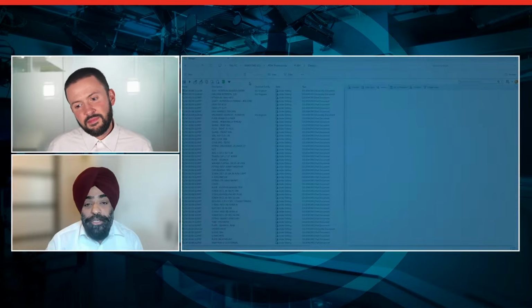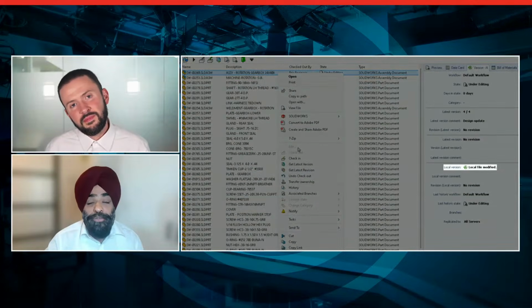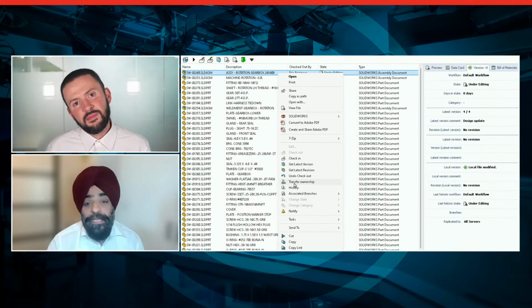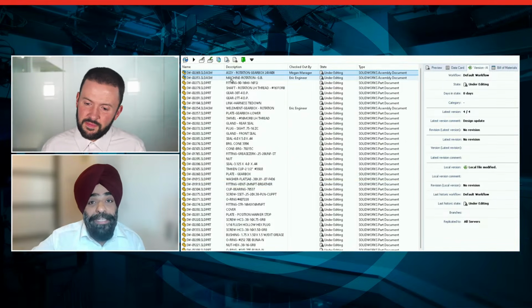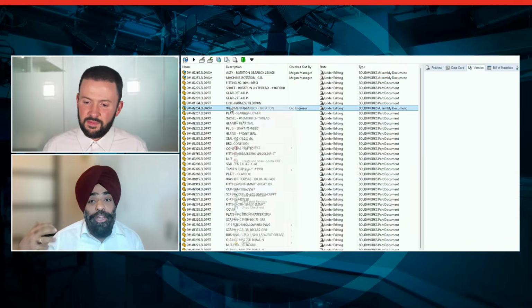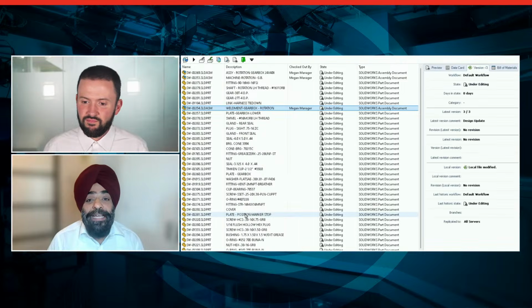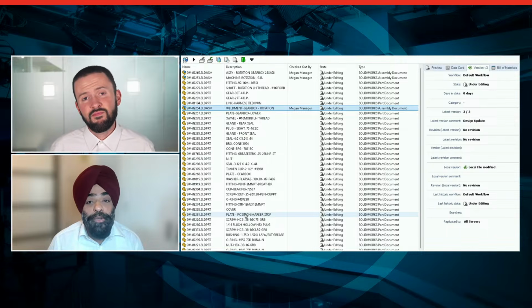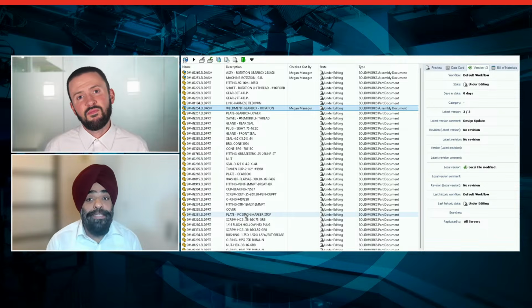So we are in a situation where Eric has either left the organization or we end up in a situation where we have a user machine crash. In such situations, we have some data which is locally saved, but it's not checked in into PDM. And traditionally, we lose that data. So what's new in 2026 is the ownership transfer, wherein a manager can transfer the ownership of Eric's checked out assemblies just using the right click menu.